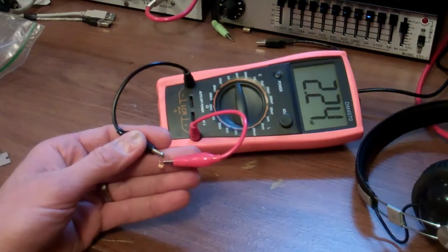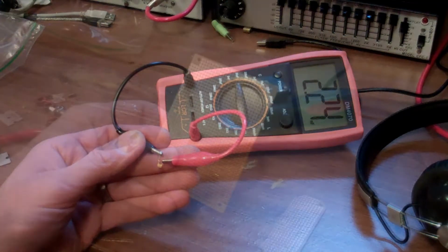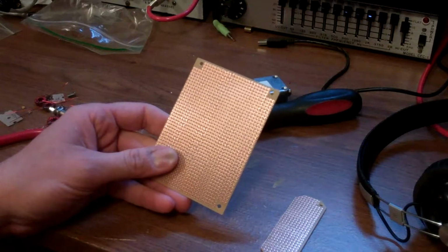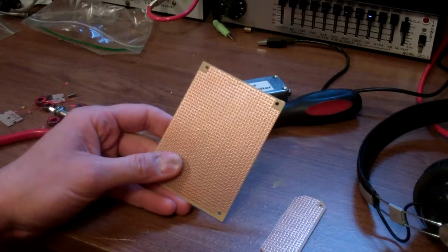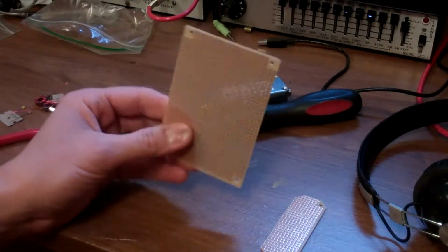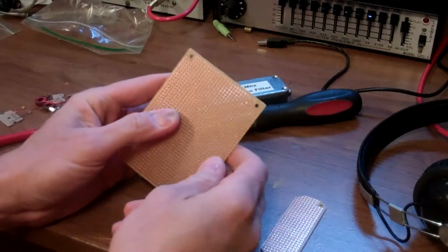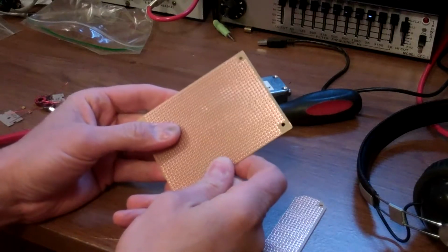Once I've finalized my toroids, my inductors, and I've measured them and I've gone back and modified the schematic, then I'll go to choosing my capacitors. And usually you have to vary them a little bit, but I'll add or subtract capacitors together to get closest to the correct value. So once I've got all my components finalized and gathered together, I'm getting ready to start the assembly. I usually like to use one of these little breadboard PC boards as a starting point.